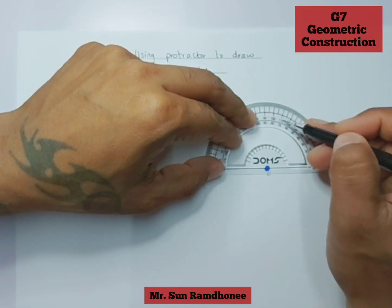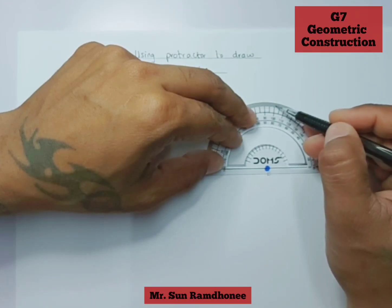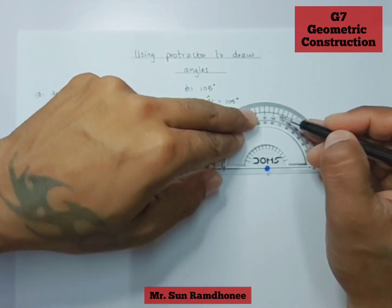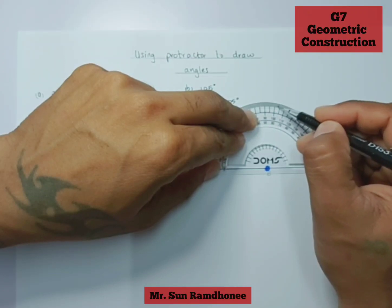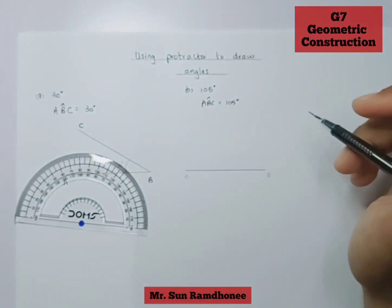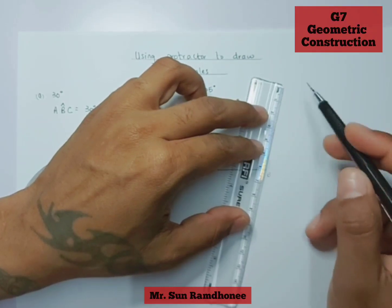Next we have 105, which would mean that similar to the ruler, there are 10 divisions. And this is the 5th division that is missing. So we are going to count 100, 101, 2, 3 and 4 and finally 5. So this is 105 degrees. We're going to draw the line from point B up to here.